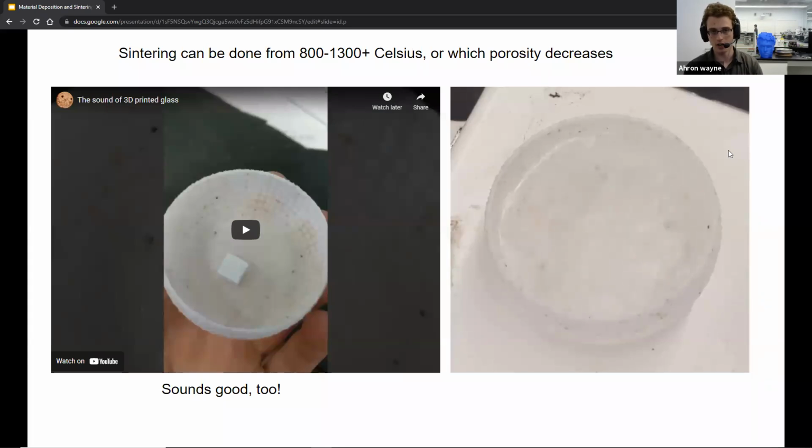And then the main trade-off behind whether or not to go right up to the melting point is warpage versus density and strength. The higher the temperature, just universally, you'll get a denser part, but it will warp more. So it all depends on how stringent your part has to be. If your part absolutely needs to be a certain shape, you can get a very precise shape like that bolt that I made, but you just have to print it a little bit cooler. But then, of course, you're trading off the density and strength for that.